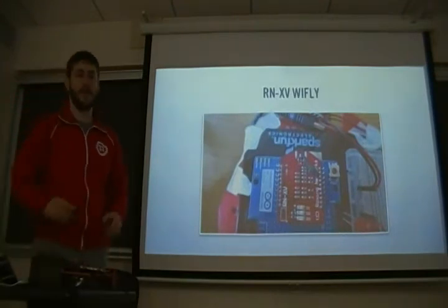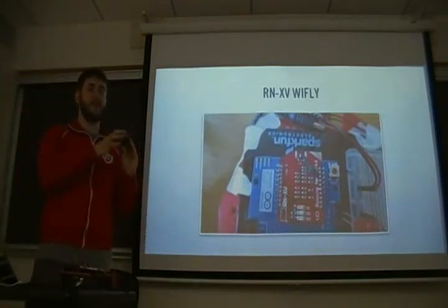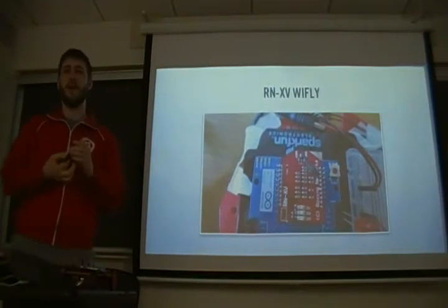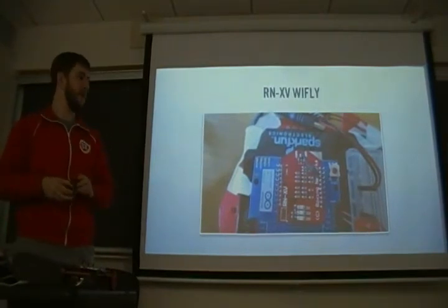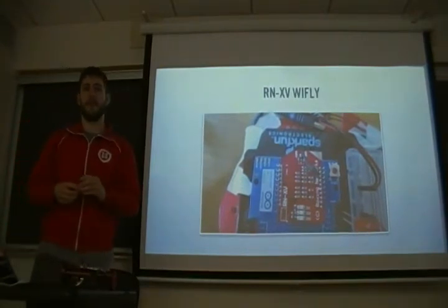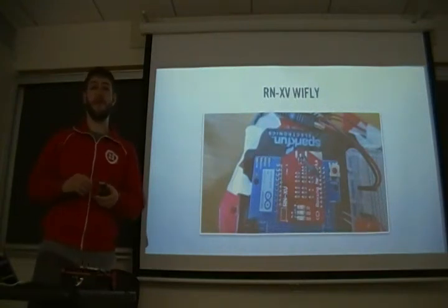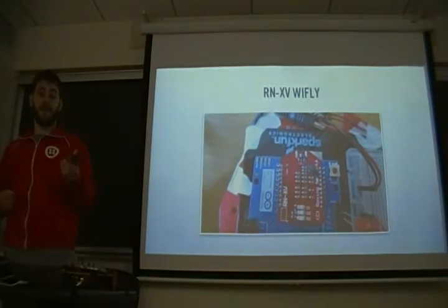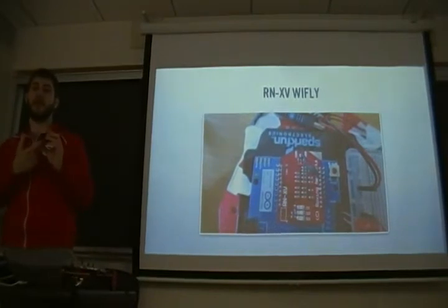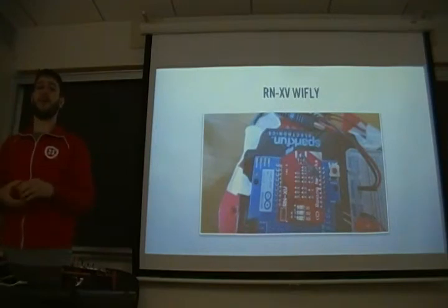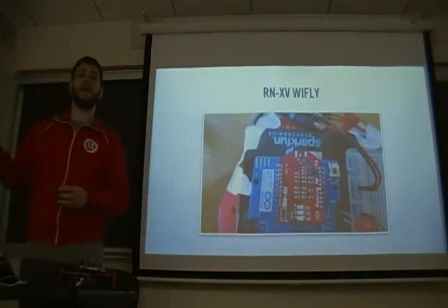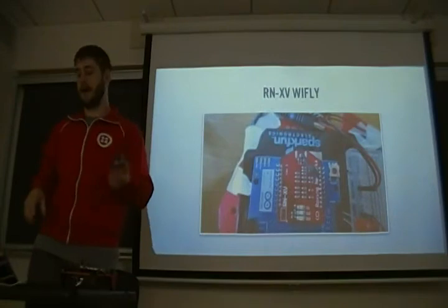Then we have the Wi-Fi chip. As I mentioned, it's a form factor that's pretty common in Arduino, but this one happens to be for Wi-Fi. It's kind of an interesting chip because you communicate with it via serial. If any of you have ever used a terminal somewhere, that's basically how the Arduino talks to this Wi-Fi chip. It's sending it commands like connect, or send this data, or open this IP address. It's all text-based.